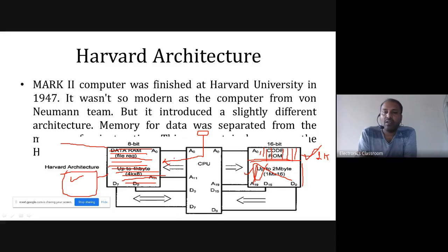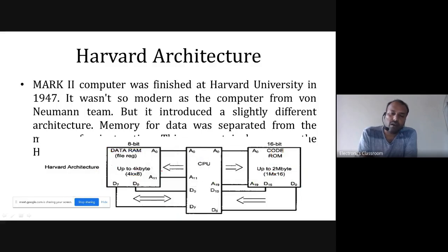Or suppose there might be another case, where you are not using data memory in your application. For example, you are writing a program to toggle LED status. In toggling LEDs, we will not require any data memory space. But let us assume that there are various steps, and those steps have completely filled the code memory.